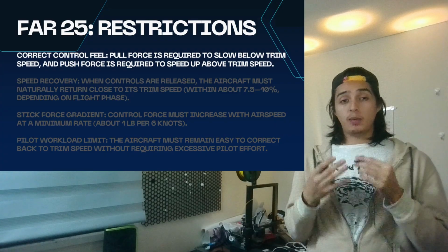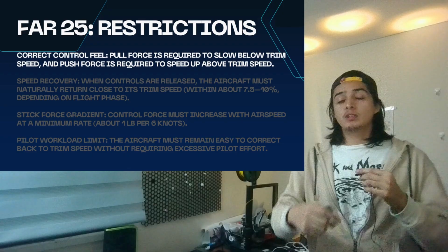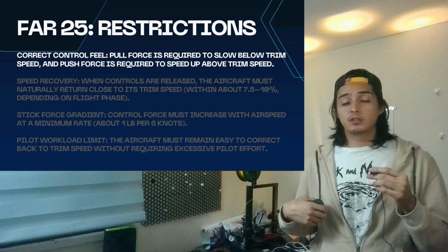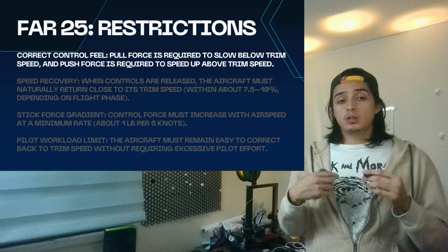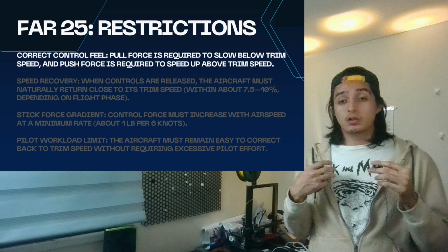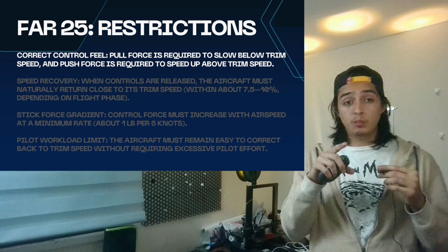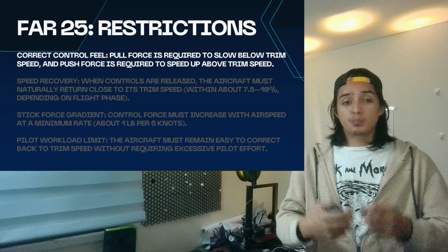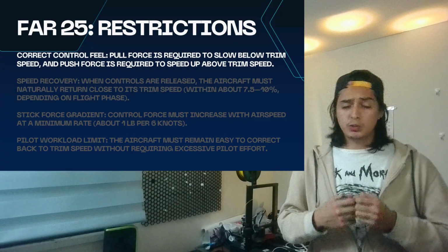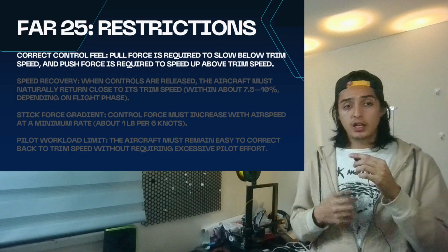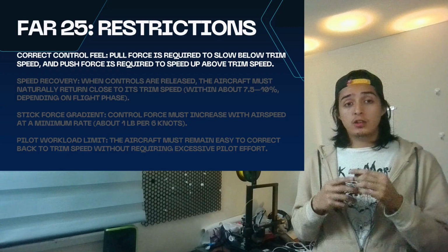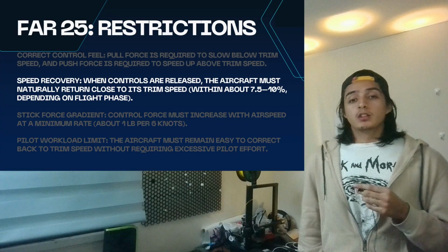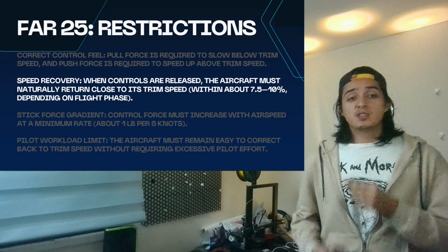Imagine that you are the pilot. If you decrease engine power, your aircraft will start flying slower, so you will generate less lift, so you will start falling. Now your nose will point down, and you will naturally tend to pull the stick, so you change your elevator position, you start getting more lift, and you can come back to the trim angle at a lower speed.